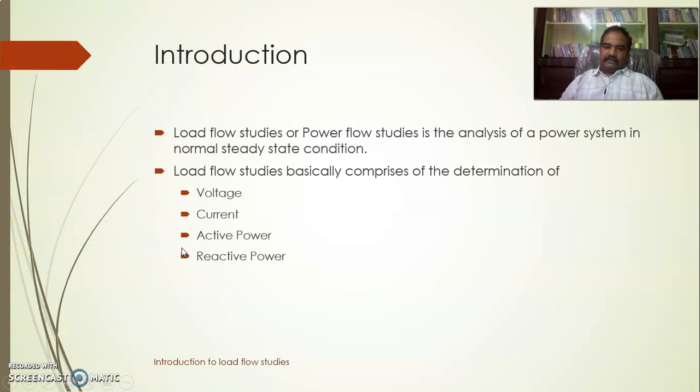Now, moving ahead, load flow analysis of a power system is basically termed most of the time as the analysis of the power system in its steady state condition. Assuming that the power system is not experiencing any disturbances and is operating steadily, the analysis of that power system, which is in pure steady state, not experiencing any external or internal force, is called a load flow study.